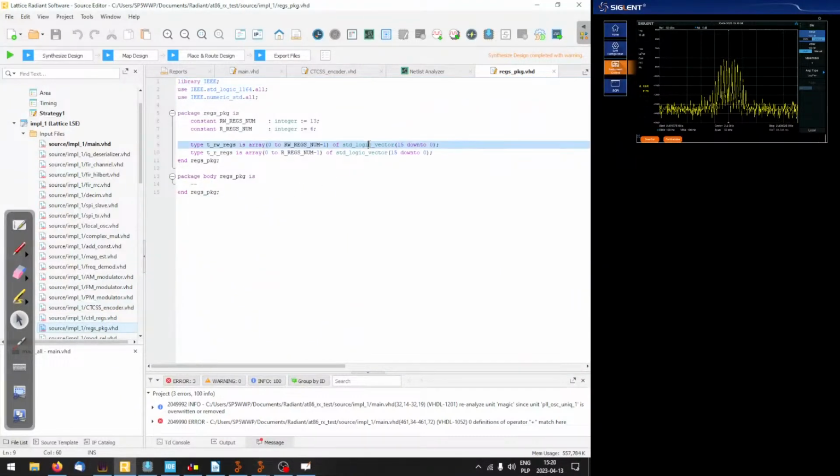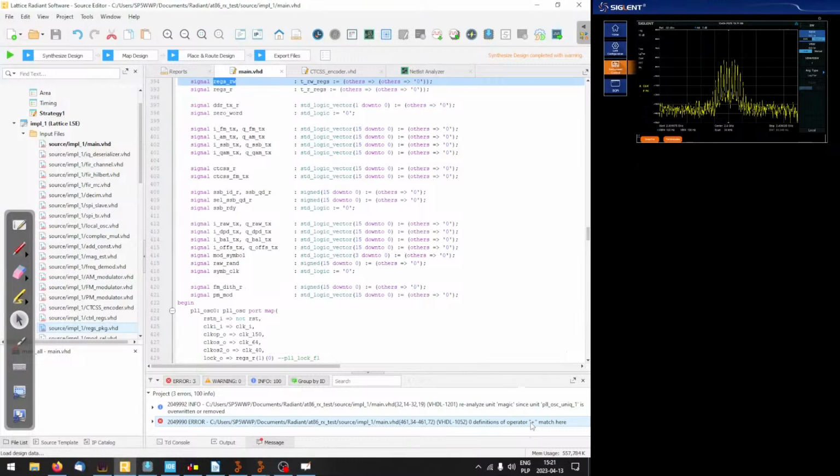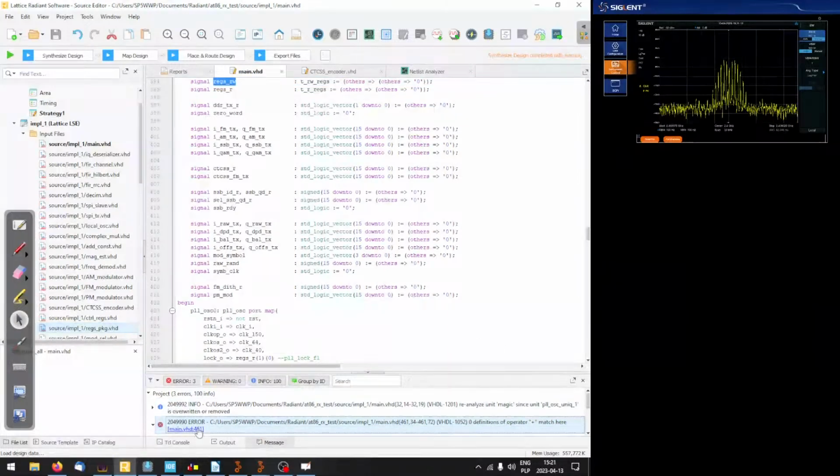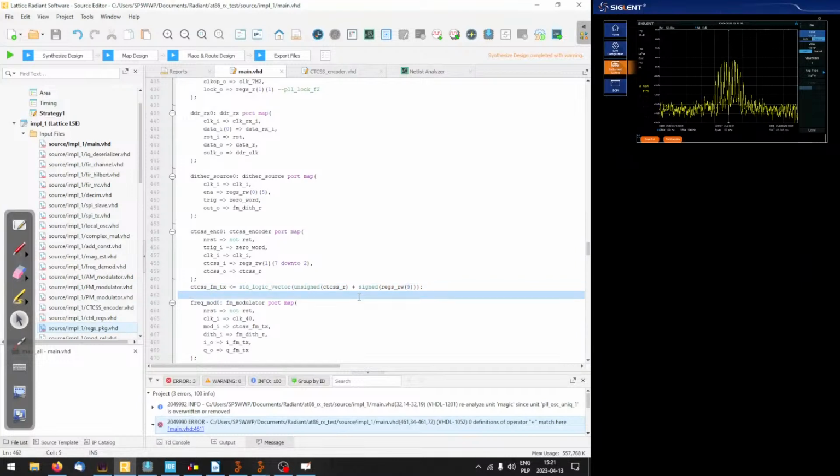It's an array of standard logic vectors. Yeah, as expected. So back to the error. Of course, oh yes, we can click on it. So what's going on? We've got the two logic vectors cast to signed and unsigned, and you just can't add them together. And the size matches because that's 16 bits, that's 16 bits too.